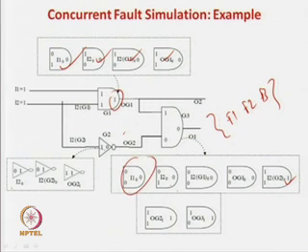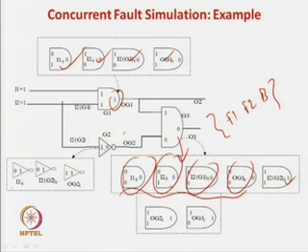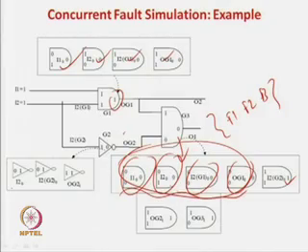Here you see we have 1, 2, 3, 4. So, 4 gates are unnecessarily hanging over there, but they are not detecting your fault. They have nothing to do, unnecessarily they are occupying your memory. But we will see in the next slides that because of these things some information is retained. That is, now if we change the value from 0 to 1 or 1 to 0 whatever, then we need not recompute the whole thing. We will just recompute whatever changes have happened over here. Only those things will be recomputed, and that is like an event driven simulation, something will be saved.